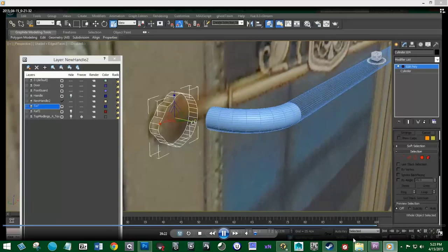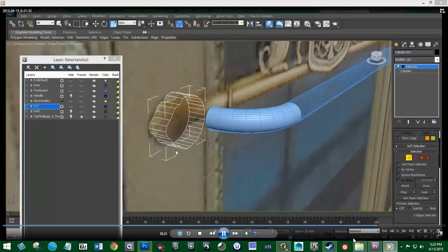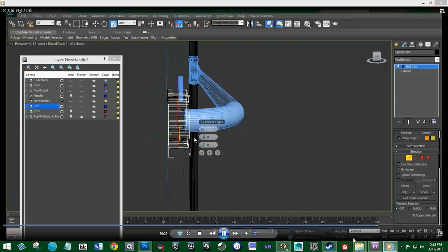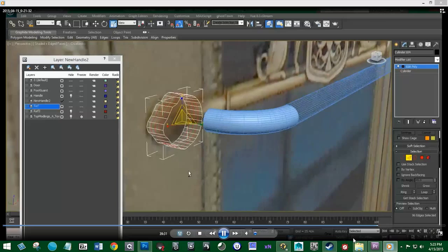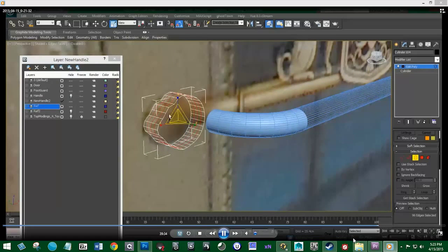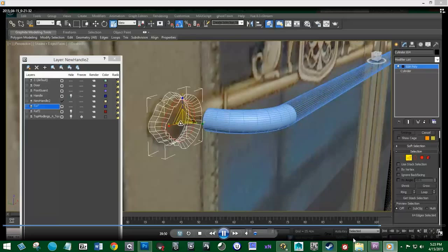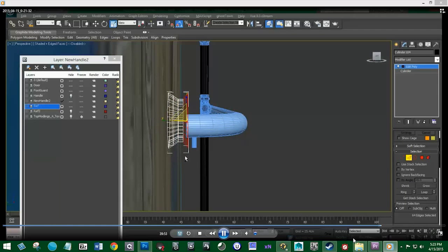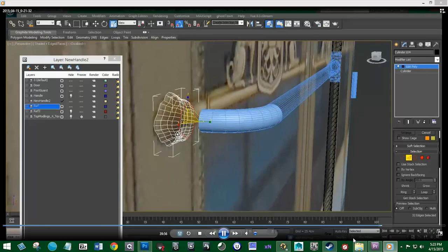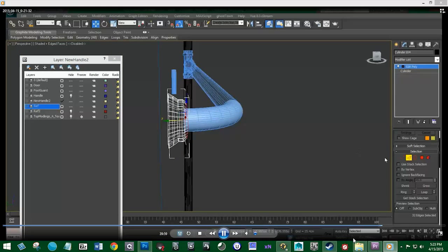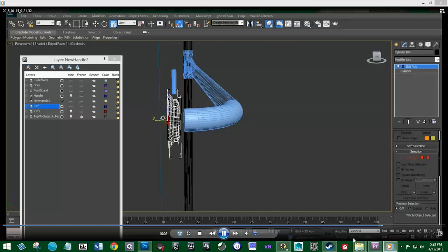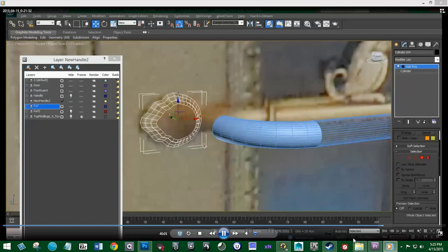I'm going to go ahead and take this and scale it up, and then take these sides and connect them and make 2 or 3 different edge loops. Try to select this one here, but that's not going to work out. So we'll just select each face by itself, scale these in since they're still selected, unselect these with Alt, scale these ones in, unselect these with Alt, select these ones, and then unselect those and scale it in. And now we're getting more of a shape of what the actual thing looks like. It's a little too thick, so I want to scale it down a little bit.